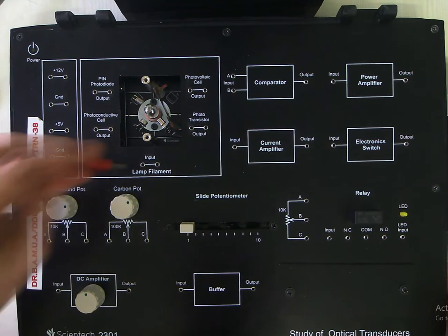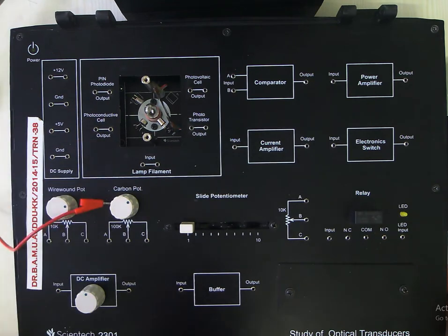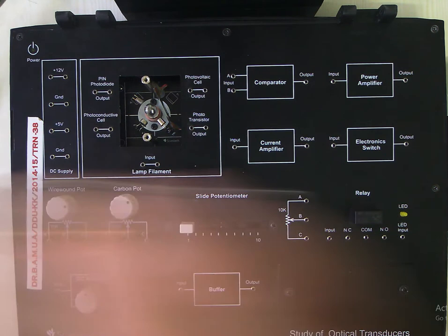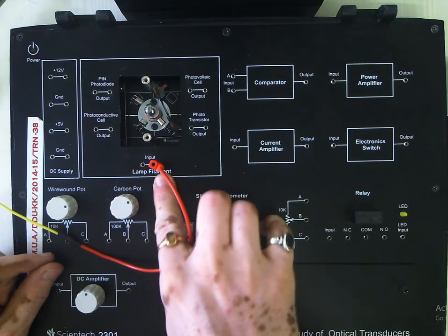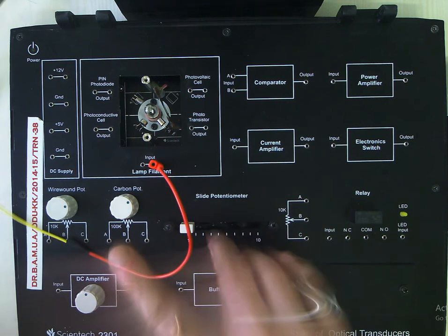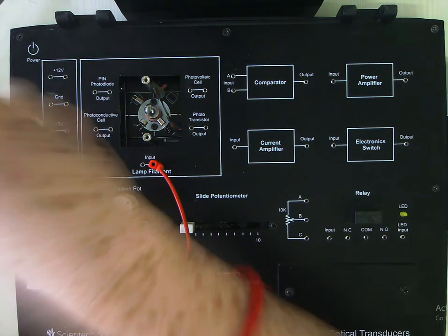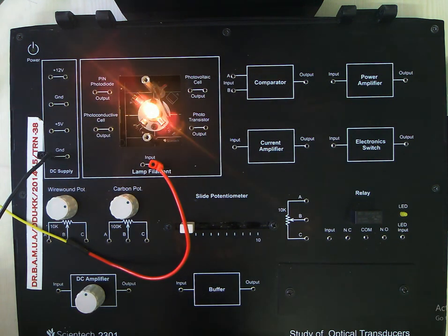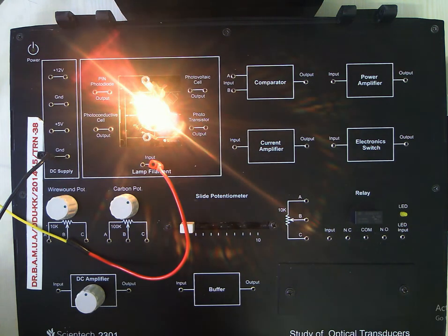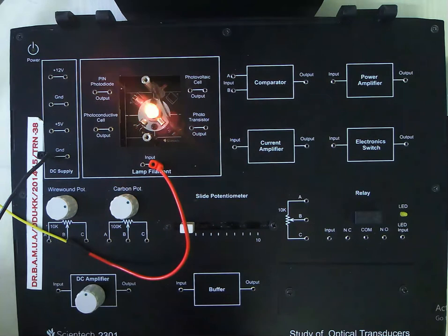So you see, I am using an external power supply. Simply that's a variable DC power supply. So I am connecting the positive terminal here to the filament, and then I will be connecting the ground terminal. So this is ground. All right. I can simply increase the voltage. I can apply up to 12 volt. That is the limit for this lamp. So you can see the intensity is gradually increasing.